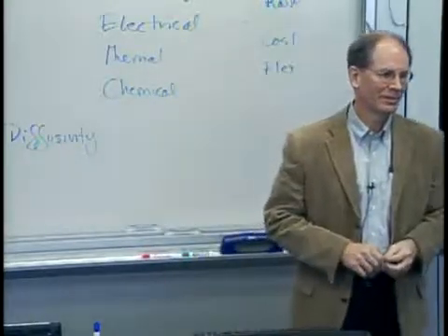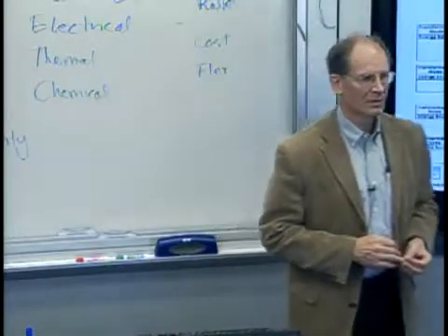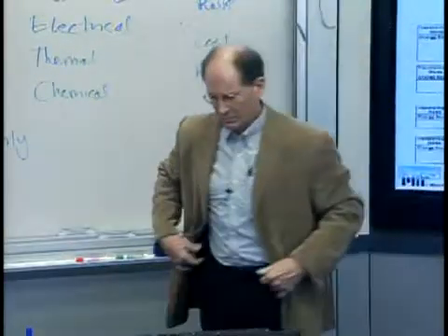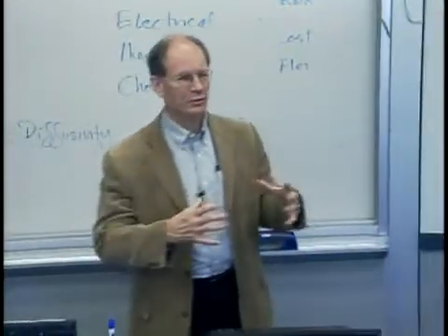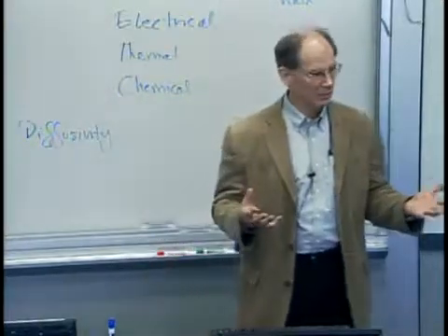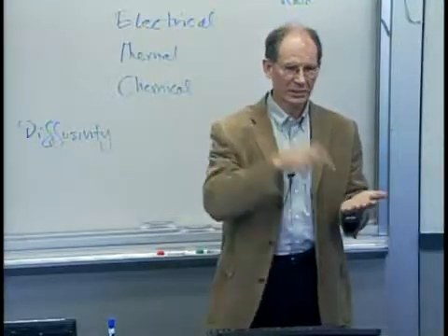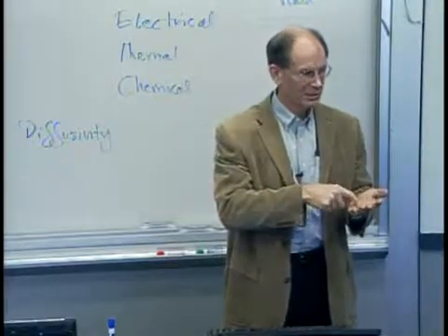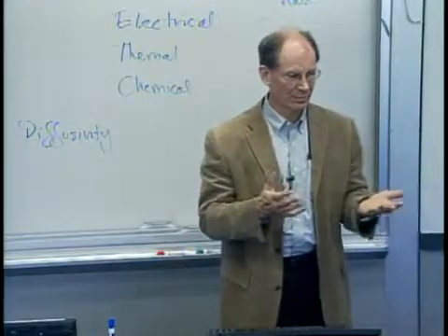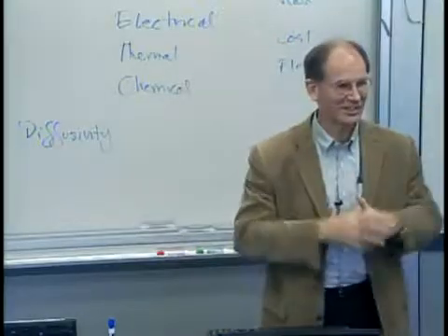Yeah, Adam. I don't know what the liquid is, but you selectively harden that liquid material with the laser. Yeah, that's right. There are these photocurable polymers that are in a liquid state at room temperature and with just regular light on them. But if you hit them with the right wavelength of light, they will polymerize. They're UV curable polymers that are used for a lot of things, like contact lenses and things like that.